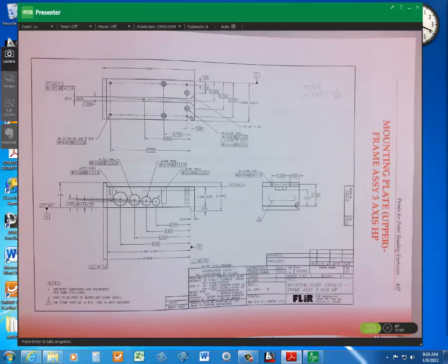So what is doing the positioning on a counterbore shape? What is actually holding the part in position? Which part of that, the top dimension or the second dimension? The hole or the counterbore? Which one of those features? The hole. It's called the pilot hole, or the hole. And that's going to touch the sides of the screw.